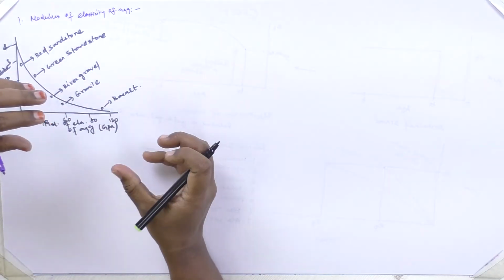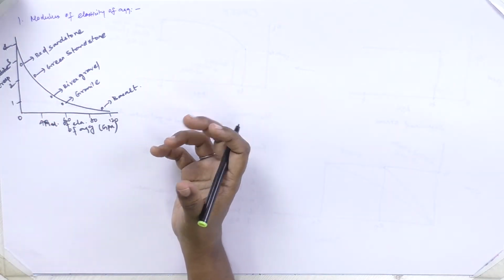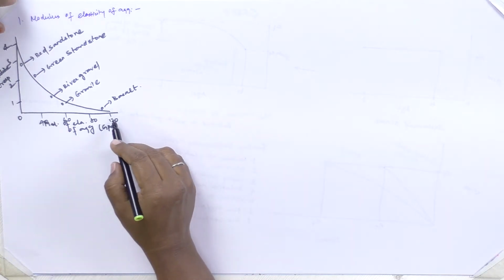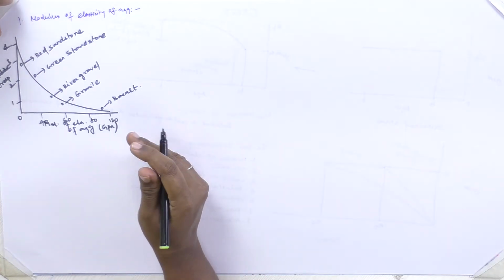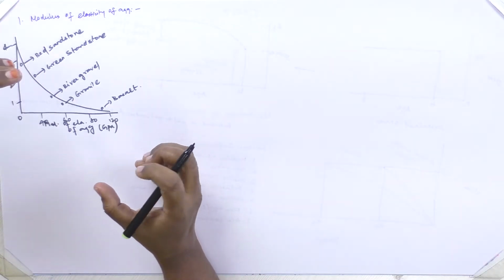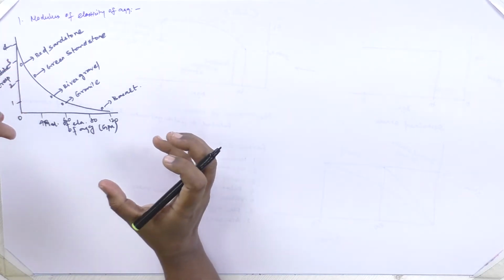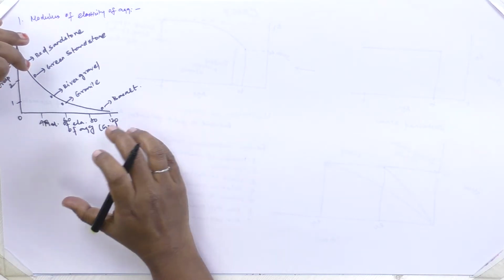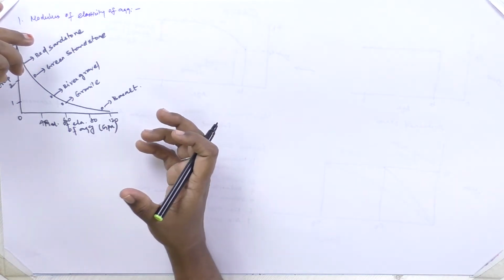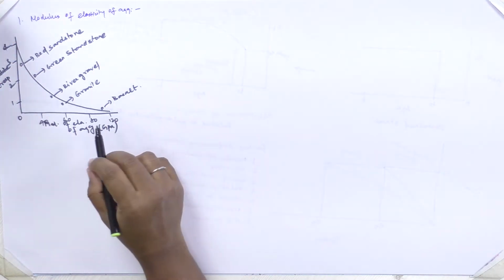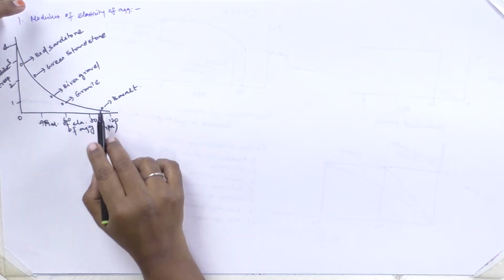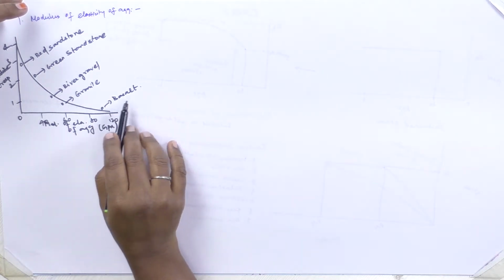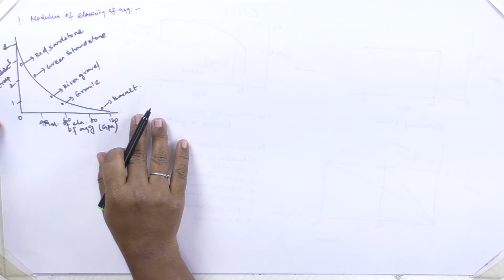The cement paste is responsible for this creep. So, when a higher modulus of elasticity aggregate is used, it doesn't allow the cement paste to creep at a faster rate, and that's the reason why higher modulus of elasticity of aggregate exhibits lesser creep.